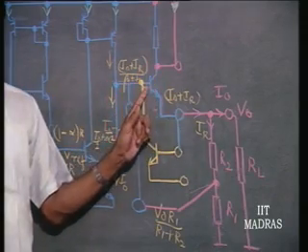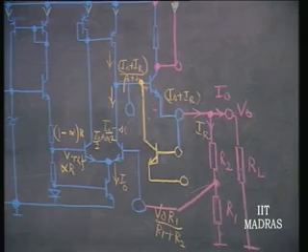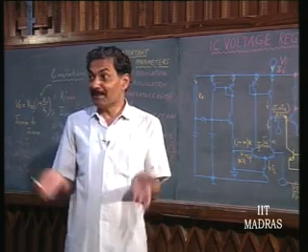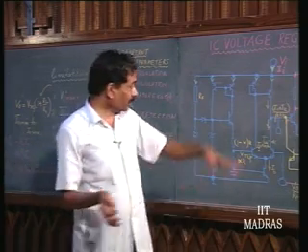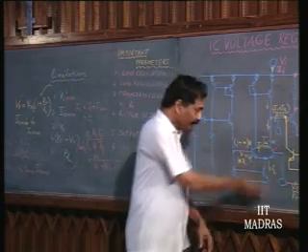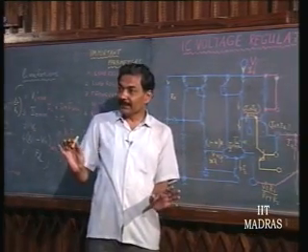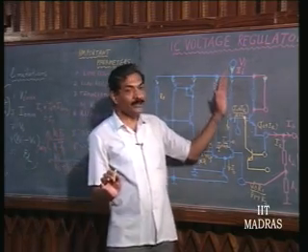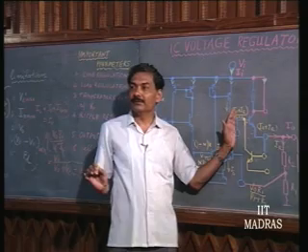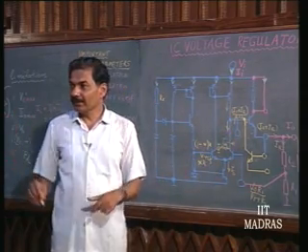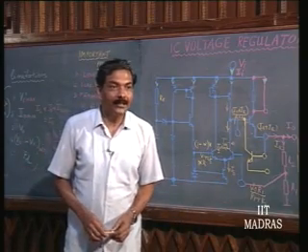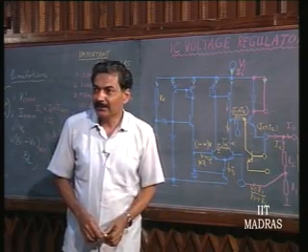So, I naught is going to pump it into this, therefore the maximum current that you can have is I naught into beta plus 1. This is the maximum current that this circuit is capable of giving with this differential amplifier functioning satisfactorily. Have you understood this? That is the only available current to you, and that is another limitation, right. If you demand more current than that, this circuit will no longer act as a regulator, right.